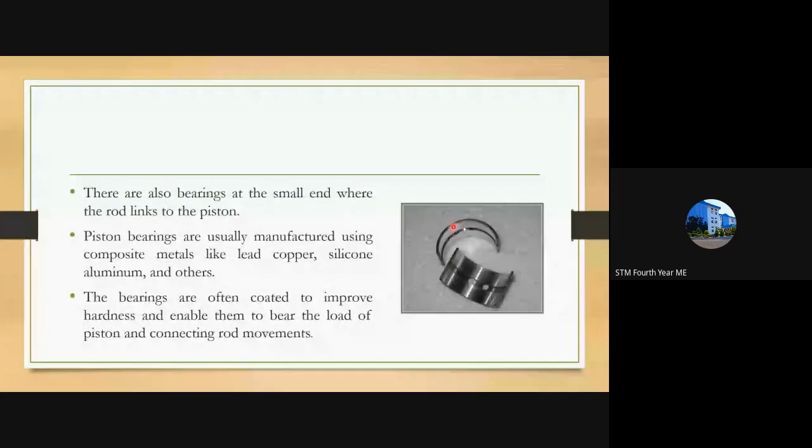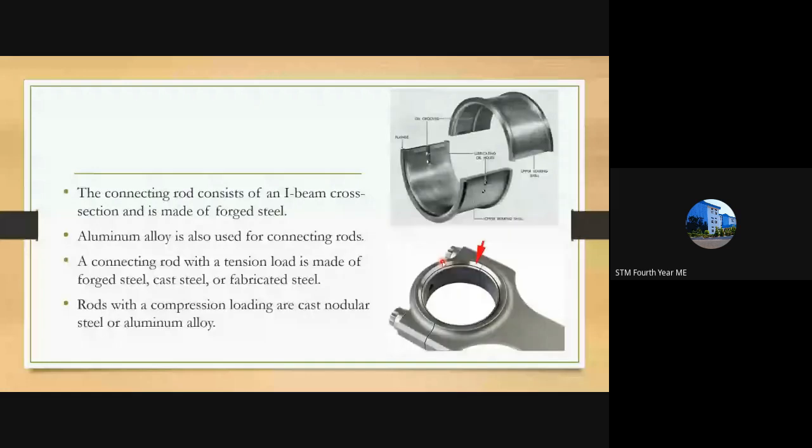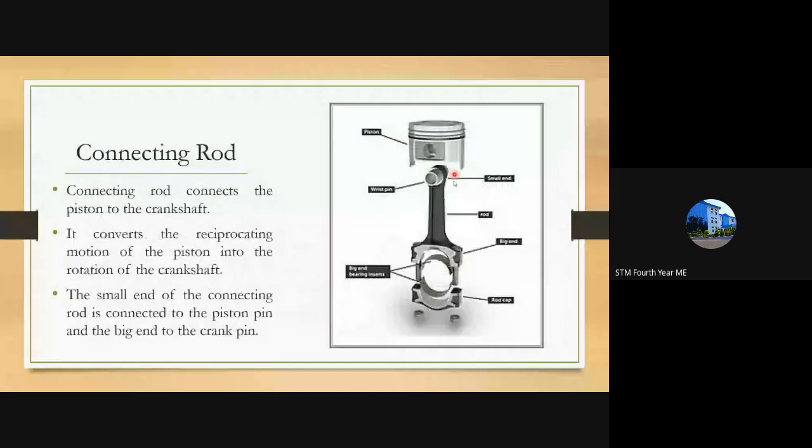Why is the connecting rod built as a small end and a big end? Once the piston receives the power stroke, it is thrown downwards. During the power stroke, the fuel air mixture explodes and throws the piston downwards. The pressure is very heavy, and the force resulting from it is very high.